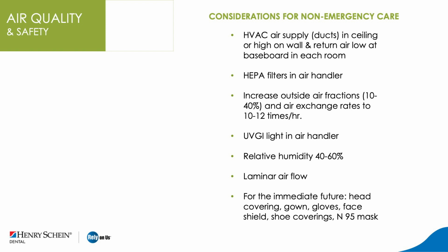Now, here are some considerations for non-emergency care. First of all, the heating and air conditioning air supply ducts should be placed in the ceiling or high on the wall, and return air is going to be low toward the baseboard in every operatory.